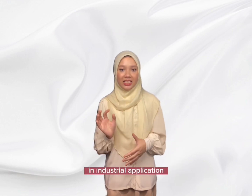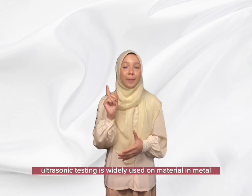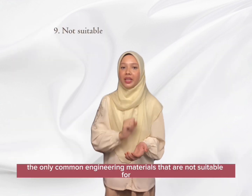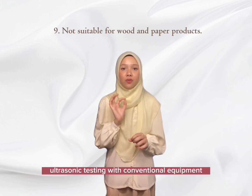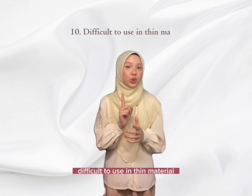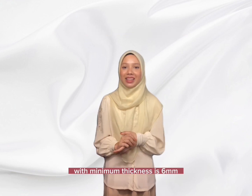In industrial application, ultrasonic testing is widely used on metal, plastic, composite, and ceramic. The only common engineering materials that are not suitable for ultrasonic testing with conventional equipment are wood and paper products. Lastly, ultrasonic testing is difficult to use in thin material, with a minimum thickness of 6 mm.